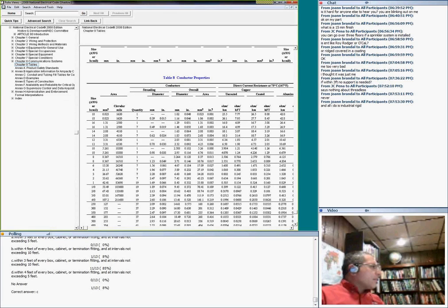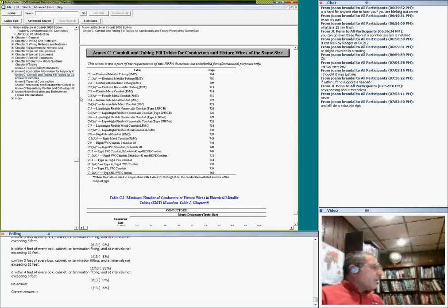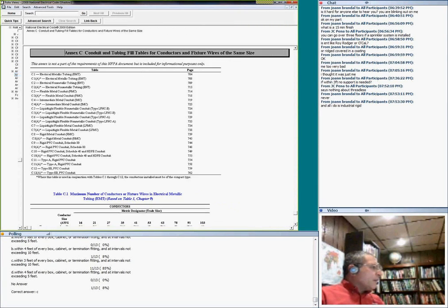The thing I want to show you guys here: if all the conductors are the same, you click on NEC, and here you go. The NEC has EMT, all the conduits approved, and how many conductors you can put in them. If it has that little asterisk next to it, this means the conductors are compact. The insulated conductors must be compact. These are special, small-size conductors that you can use for retrofit.